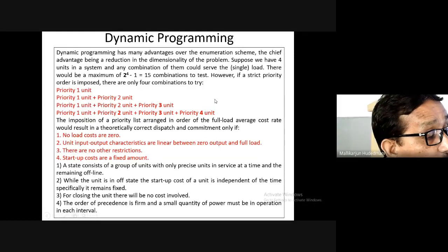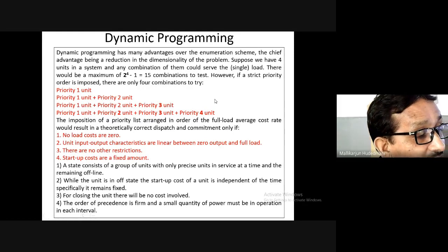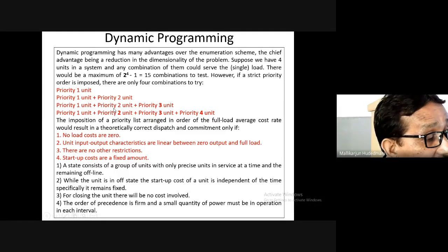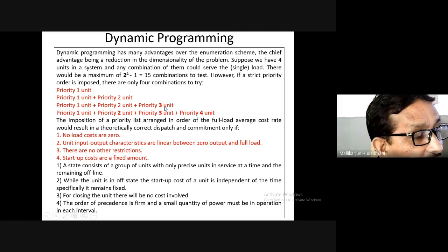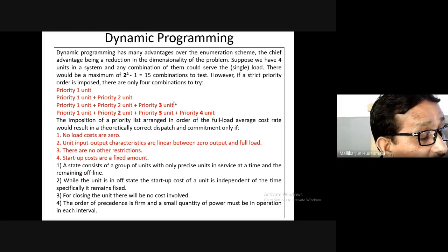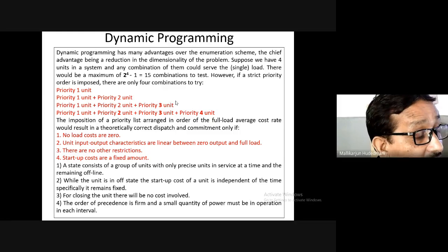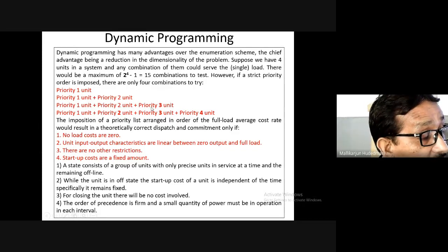Which is that you take now? Among the 2 generators, whichever is the cost effective best one, you will combine. So that becomes the 3rd decision. While taking the 3rd decision, you are left with 2 generators in the decision basket. Whether you take the one or the later one doesn't matter. What matters is what you pick should constitute optimality on the decision taken previously.